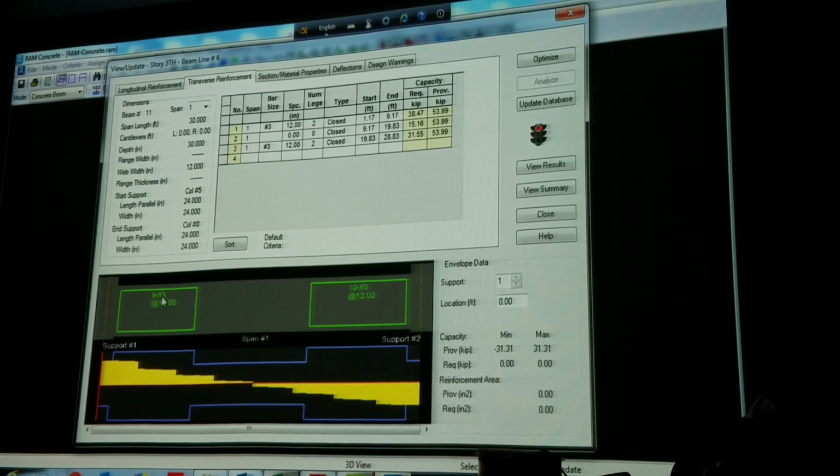If you do that, number 3 at 12 inch, or you can place up to that length 9 number 3s. So that basically is 12 inch. Here again number 3 at 12 inch. In the mid span, technically you do not need any stirrups because the shear is very low, and the concrete itself can take it. But since it's a program, we override that.